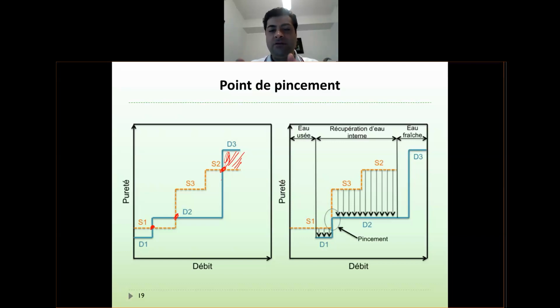But by looking at this curve, you can see that these supply streams can supply the water for the units that need water. So you again have this kind of overlapping for water pinch. By doing so, similar to thermal analysis, you end up with two overshoot units, zones.